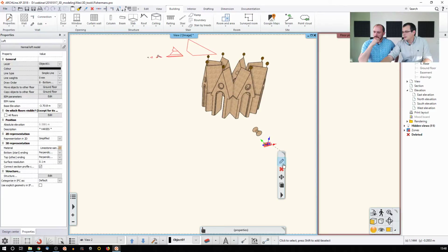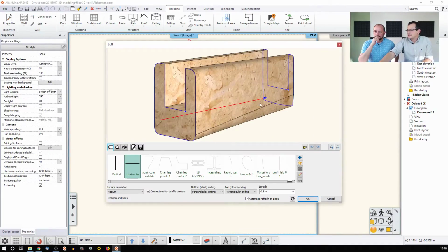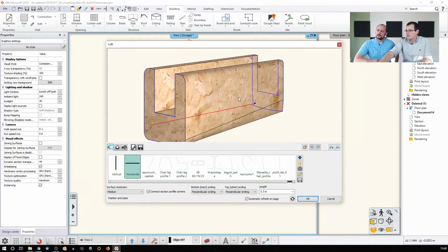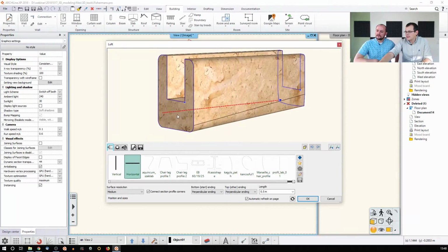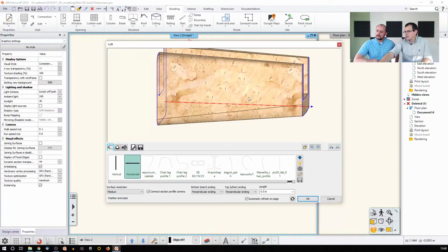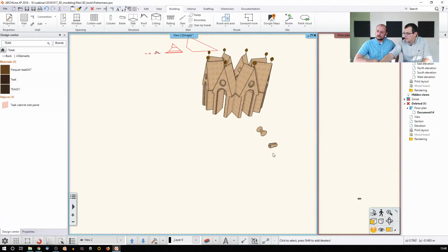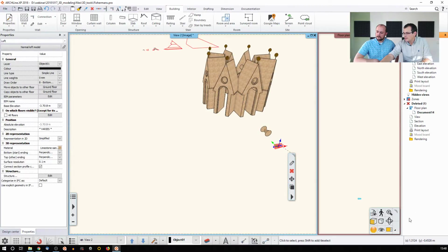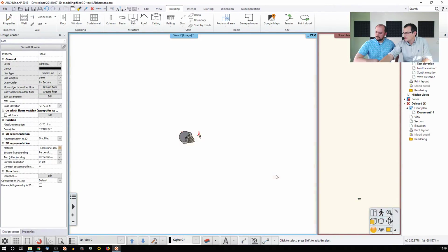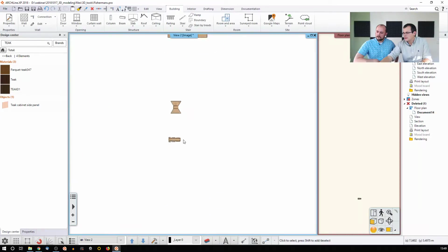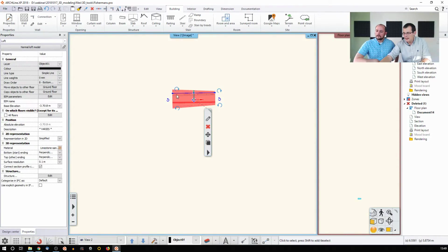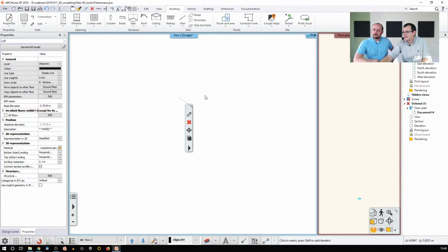So this is the object, and it's very interesting that this is actually a loft tool. So what happened over here is that there's one cross section here and another one here, and the changing size gives the shape. One great thing about the loft tool is actually, maybe if I set this to axonometric, I can show you a bit more effectively. So if I select this tool and I hit the Alt key, I see the, sorry, I just need to have another rotational axis.